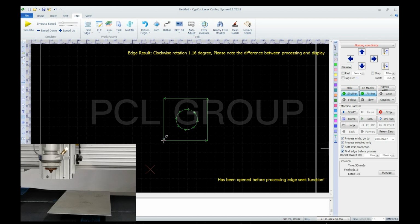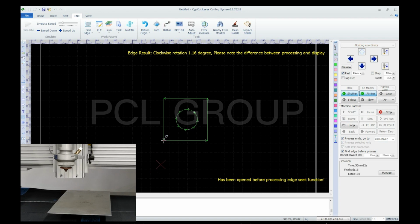The laser head will find the edge before processing if we don't need to do it instantly. But no matter what, do make sure there is a plate right below for the head to follow, or the head may get damaged. When we cut sheet metal, we recommend a 6-point find edge with higher accuracy.